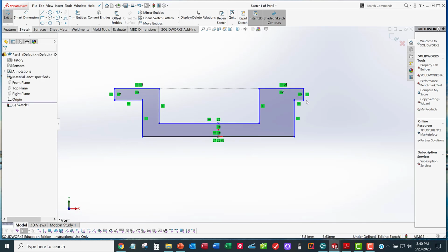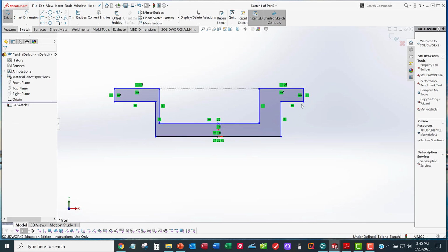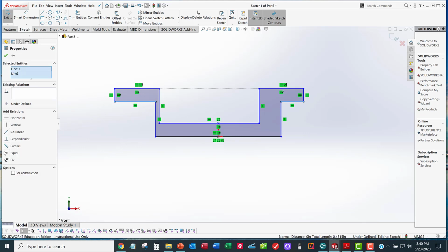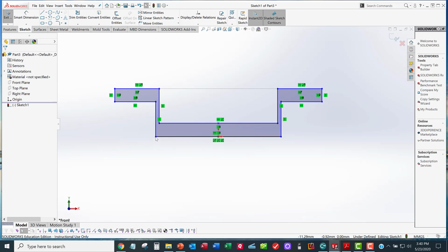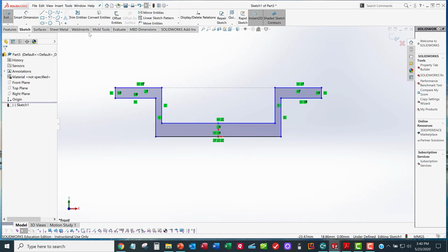And now I'm going to do a similar thing over here. This is symmetric here, and so I want this line. Control-click this line. Make these equal. I could do some combinations of symmetry constraints, but like I said before, there's more than one way to tie this down. Now this thing is looking like it's geometrically constrained, and so now I'm ready for some dimensions.